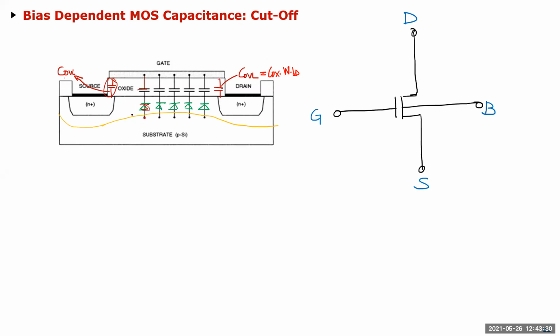the substrate. So like I was showing when we started the class, I was doing some problems. So basically the gate to bulk cap is 2 caps, and this is C ox, and this is, let's say, C depletion, the depletion cap or the junction cap. And that's this cap. And then on the drain side, same thing. The cap is only this overlap cap, because now the channel is not formed, so you don't see any of these fields get terminated to the drain side. You don't get any of these fields terminated to the source side. They all get terminated in the substrate, and you have a substrate connection.